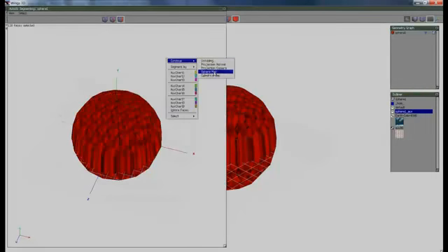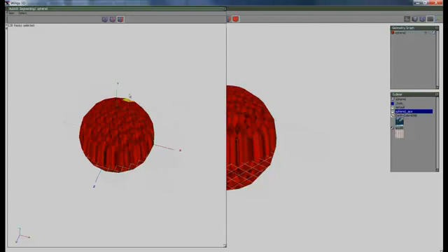There's two left, there's sphere map and cylindrical map, and if you think a little bit, a cylindrical map is actually what we want. Because you have to imagine a cylinder being around this mesh and that being used to project onto.